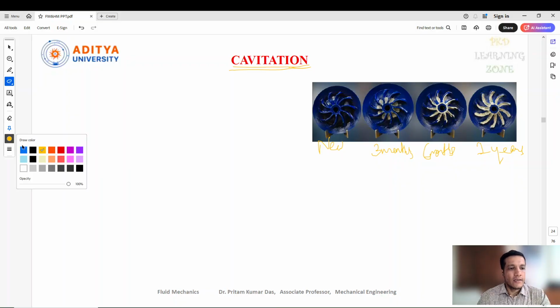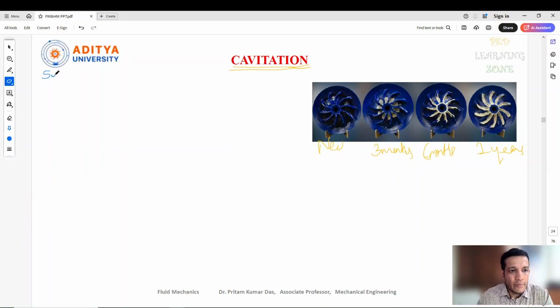For that, let's discuss some other things. What are the symptoms of cavitation, so that I can identify them? What are the indications of cavitation, so we can identify that cavity formations are there and avoid them. The first point: the fluid flow rate will decrease.